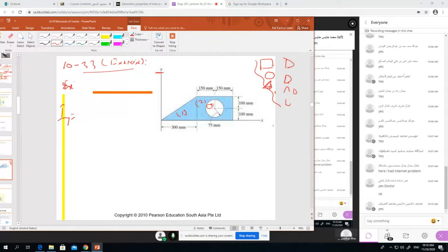For the triangle, we learned the formula. If the axis center is here, Ix is here, so through this center, there is 2, right? Because we are calculating Iy, we will consider this one. And for Iy we learned BH cubed by 36, for the triangle, right?